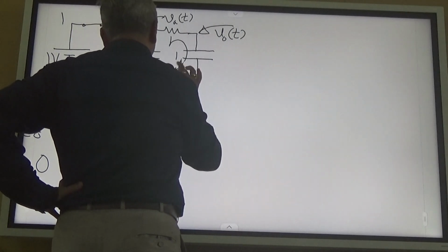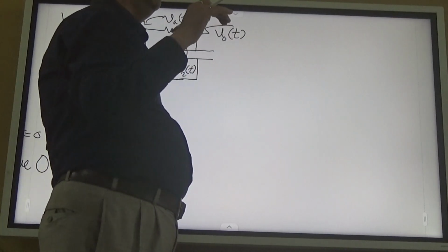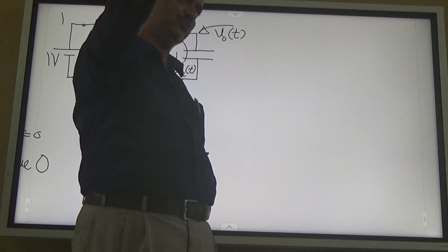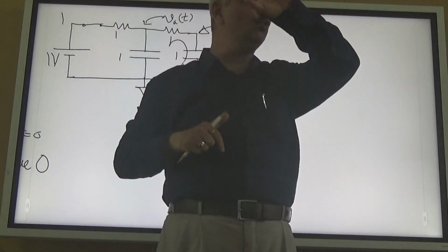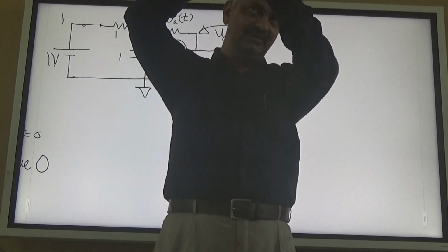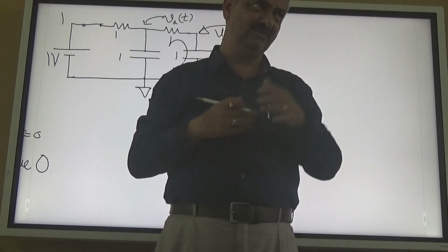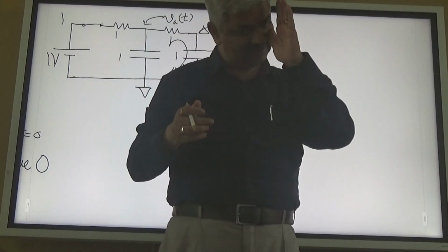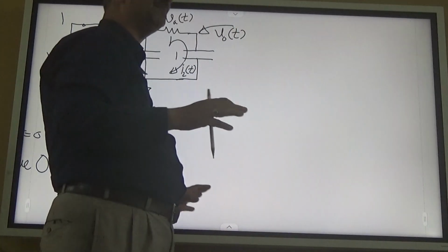Now, how do we choose currents? When there is a system, you can choose some and use Kirchhoff's law. At one node where 3 branches are coming, 2 you can choose, and the third you can consider so that this plus this equals 0. But which you choose, that is a wise decision. That comes through experience. Classically, you can choose anything and you will get the answer in any case, but you will get the answer easier if you choose wisely. So that wisdom comes through experience.